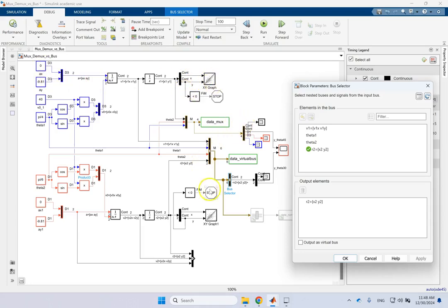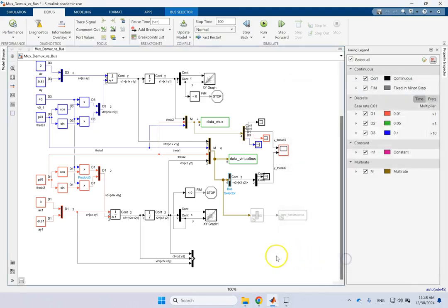I don't have to. I have 6 signals, 6 numbers here, or 4 wires. 2 of them are vectors. If I want to send only the one that is called X2, Y2, all I need to do is, look here, let me remove this. All I need is, I have the names of the signals. I go here and then simply what? Click on this, out to the output. Done. You see? Okay. Or if I don't want it, I can add another one or another one.